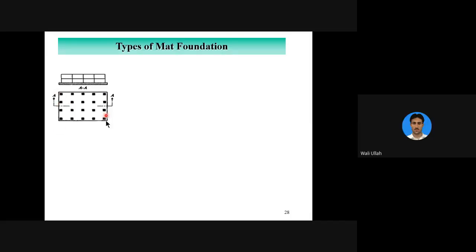No, this is a requirement when the bearing capacity is low. If you provide isolated footings, they would automatically merge with one another, providing you a single big mat.